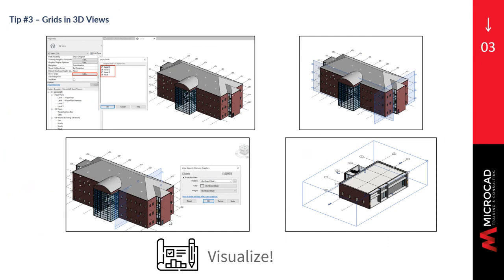And on your 3D view, you can treat grids the same way that you treat them on your 2D view. So for example, you can go ahead and hide grid elements by category or by filter, or you can use your visibility graphics overrides dialog to display information for your grids, such as showing them in halftone, or you can copy, cut, and paste split grids in your model, which is a really nice feature for 2022.